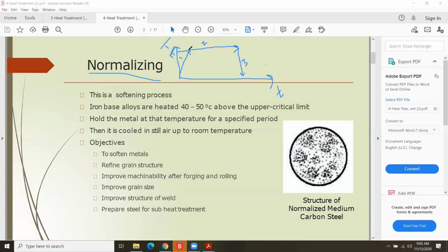So therefore you heat it to a high level of temperature. So therefore it forms austenite structure, right? At this heated level, austenite structure is formed, because we discussed earlier, austenite structure can be formed only at a high level of temperature, right? So you uniformly heat that steel to a specific temperature, so therefore it causes austenite structure, right? Then the second phase is the soaking phase, right?